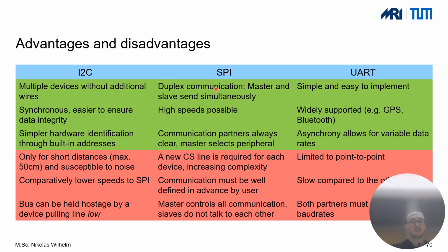And here, using more signal lines comes with the benefit of a higher data transfer speed, but of course, on average, you just need many more pins compared to the I2C setup. So you need more pins to get started, and then you need 1 additional pin for each further sensor that you use.